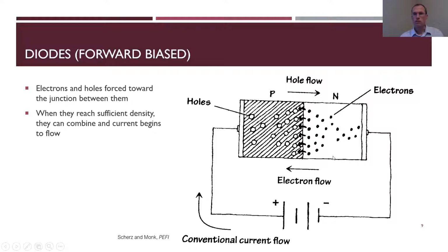So I get current in the circuit, again, as long as this battery is higher than the turn-on voltage, usually about 0.6 volts, as we saw last class or last week. If this battery is larger than that, I get a turn-on voltage and current flows.